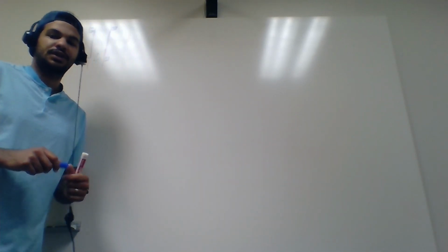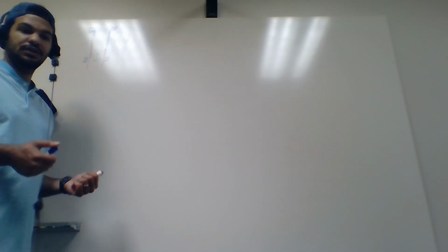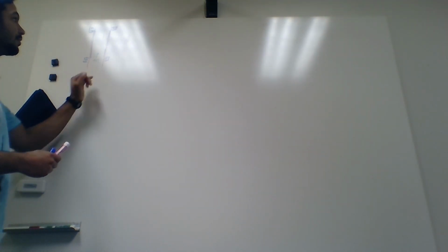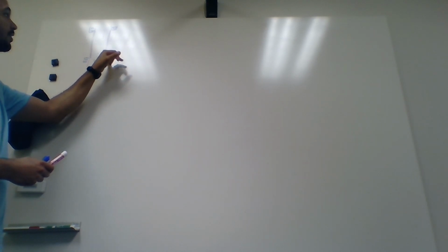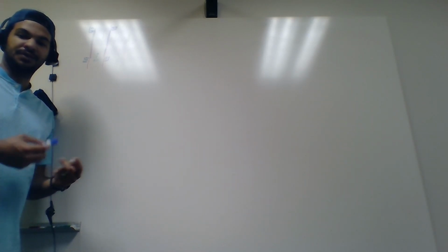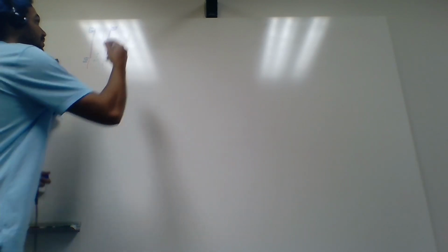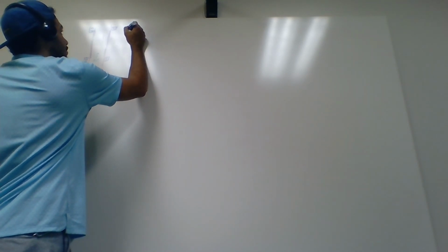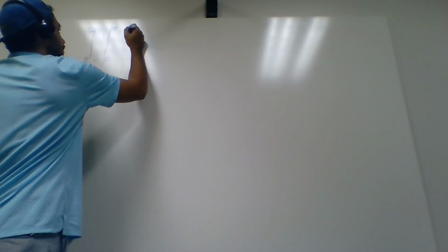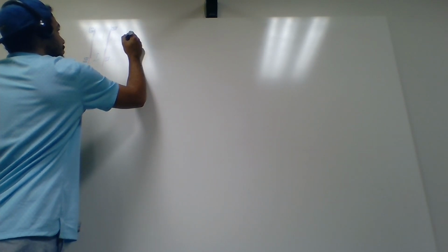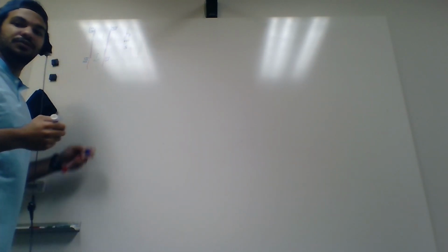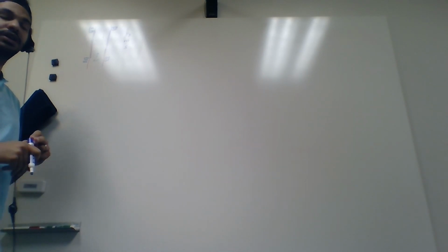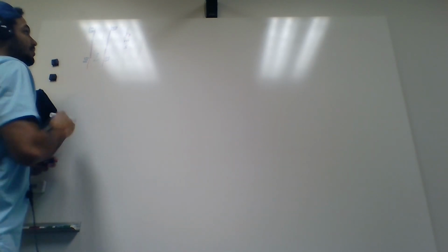So today we're going to look at the Sherwood-Gilliland correlation as it pertains to a cylindrical pipe with water flowing down the sides and air blowing up in the middle. How we're going to do that is through dimensional analysis. So what we want to look at is the three fundamental units: kilograms, meters, and seconds, and relate those to the variables pertaining to this problem.